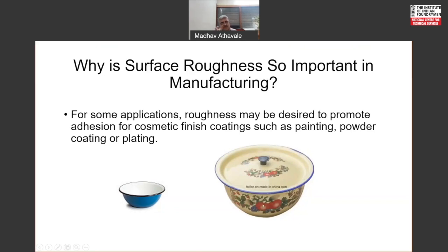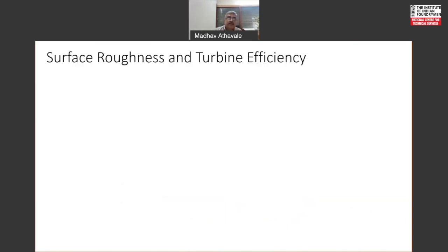And they were looking very uniformly rough, but they were rough as compared to their older plant, where they had a surface finish which was a conventional jolt squeeze line. At the bottom, it was a very fine finish. On the sides, it was a relatively rough finish, as happens in a conventional jolt squeeze line. And while talking with the foundry owner, he said he prefers the DISA because while the surface finish is coarser, which is what they want, it is also uniform. That's why it is preferred. So that was an example for me.